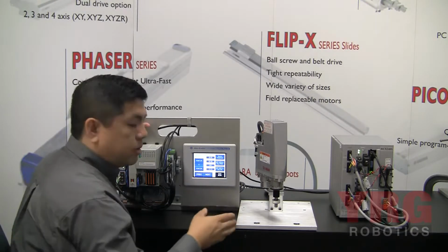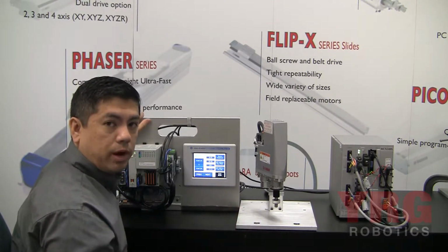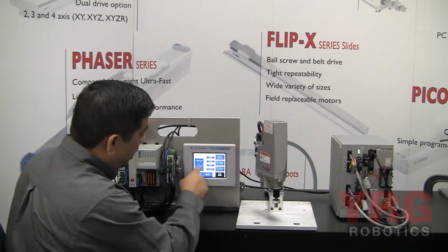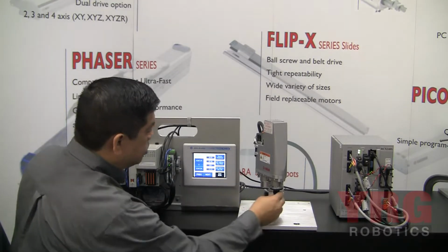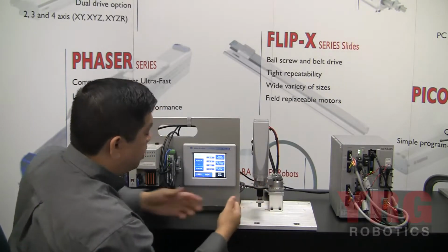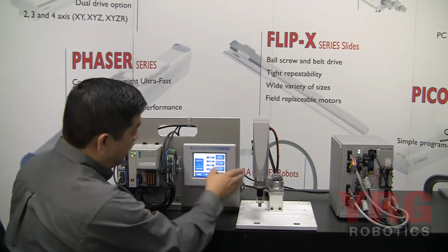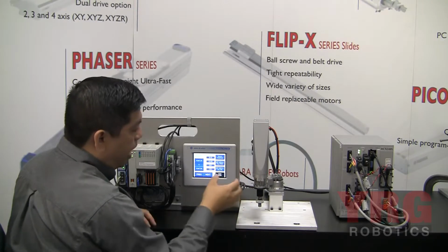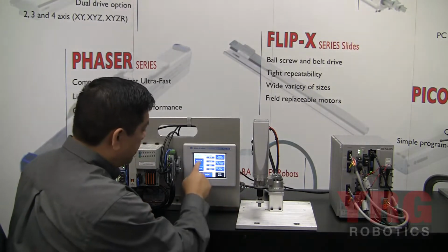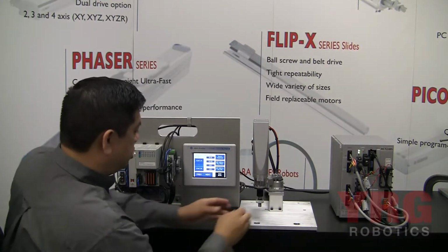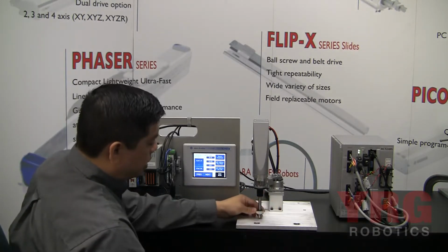I'm going to teach a quick little pick and place program, 5 points. I have a point register indexer here on the PanelView, and I'm going to store the home position into 0. I'll set the robot anywhere I want and hit teach position. We're grabbing the values of the robot right now and storing them into the PLC. I'll index my position to number 1, and I'll teach my first pick position.